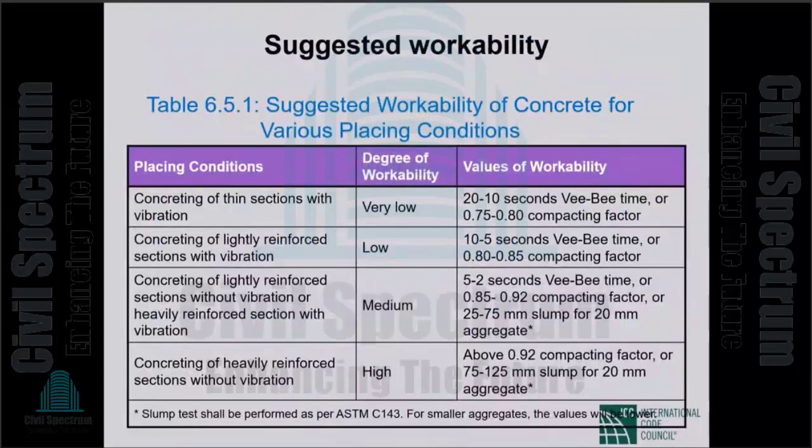Okay, BNBC has this table of suggested workability of concrete for various placing conditions. Concreting of thin sections with vibration, degree of workability is very low. You need only very low workability. If it is concreting of heavily reinforced sections without vibration, you need very high workability. You need basically flowing concrete.